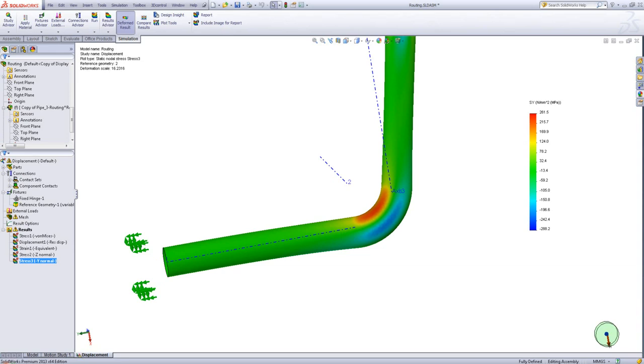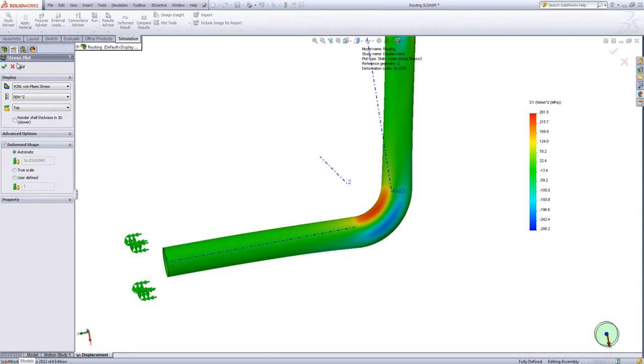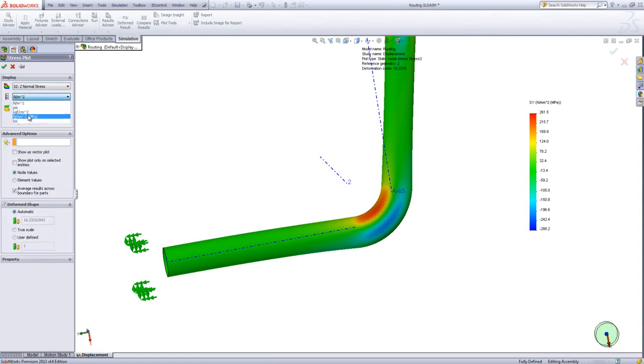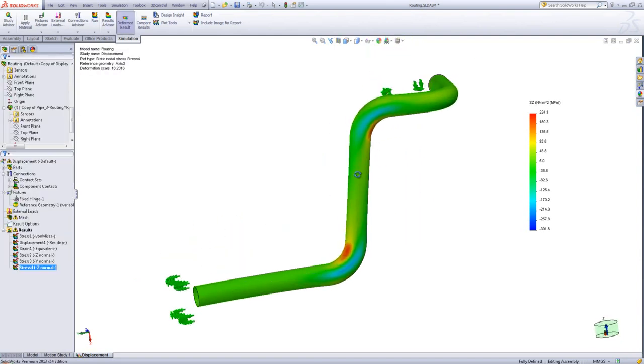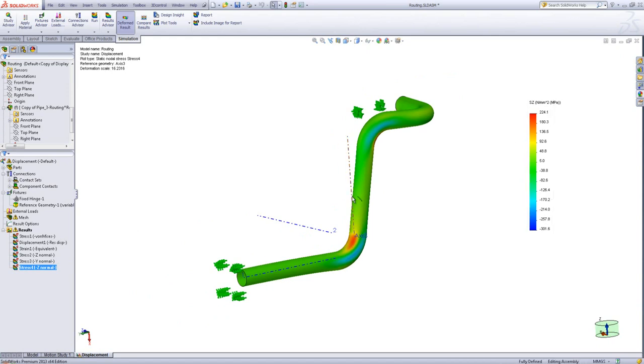Okay? And we can go on, so I'll do just the one more because we did generate that axis. So I'll take my Z normal stress, megapascals, I'm going to use axis 3 as my reference. And then we've got the stress values that are present in axis 3, on pipe section 3, sorry.